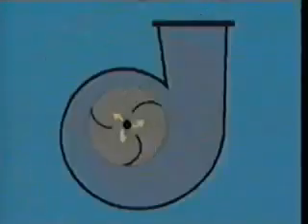Because the outside edge of the impeller travels faster than the center of the impeller, the gas is forced to increase its speed as it moves outward. The two forces, the lifting force and the centrifugal force, increase the motion energy, or kinetic energy, of the gas.